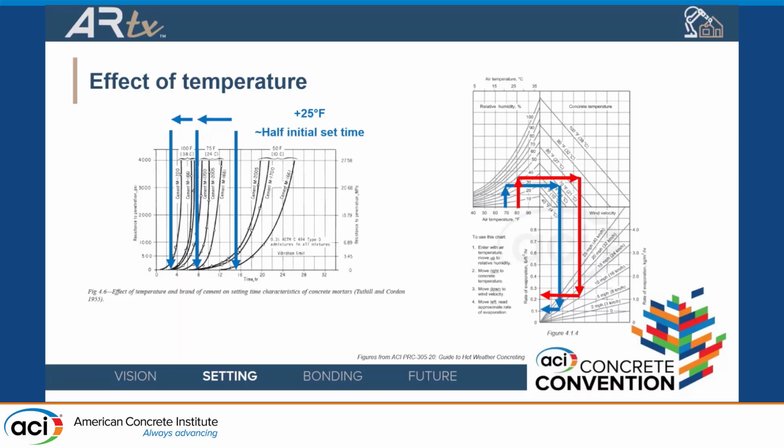the skinning over, where we can see high penetration resistance for a very small amount of distance, and then we fall down into this softer material. And this skinning, we're pretty sure it plays a big part in interlayer bonding. I'll get into what we're doing to look into that.